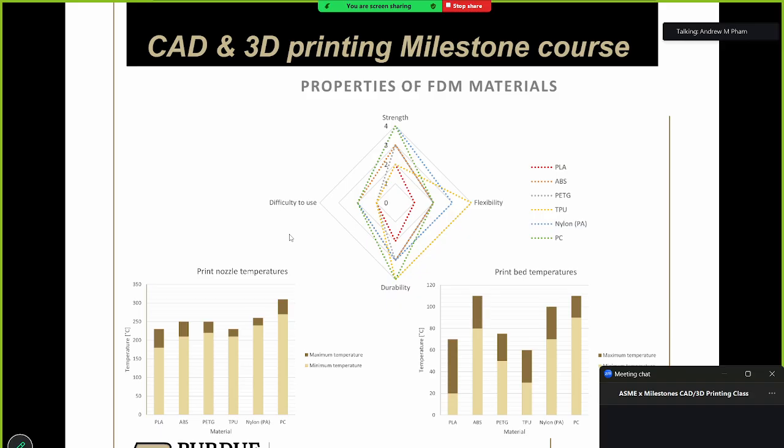I would say for the most part, subtractive manufacturing is pretty heavy duty in many cases. So, if you have a milling machine, you'll probably have some kind of high speed steel or carbide end mill. And those things usually are a lot stronger and a lot harder than the thing you're cutting. So if you're cutting a piece that is half metal and half plastic, that end mill probably won't really care. If you're drilling holes through stuff that is multiple materials, the drill bit probably won't care too much either. If that's what you're asking.